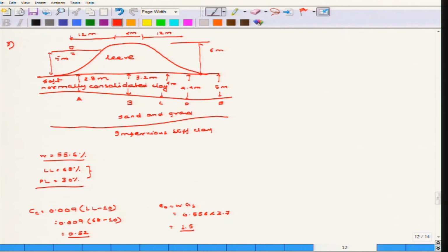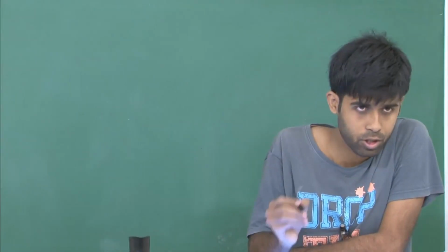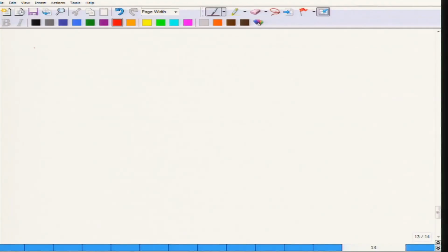H is obviously varying at different depths. The question here is how do you find out the vertical stress distribution, because, as I have said, the load that is imparted on the soil is non-uniform and the structure itself is not uniform. It is symmetric, alright, but it is not uniform throughout. So, you can use a combination of a surface strip load with uniform stress distribution.